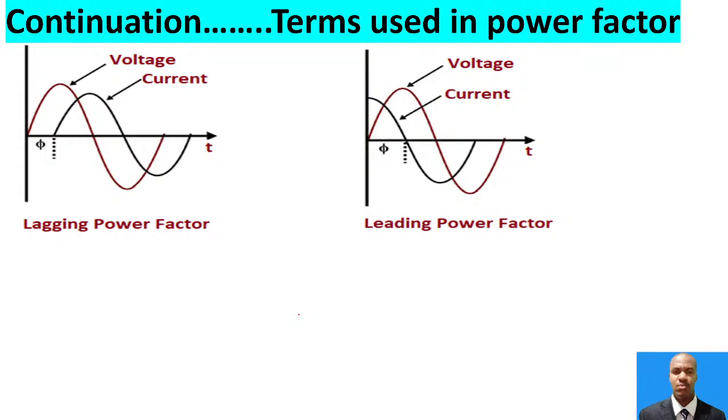And with me here is just a figurative example. If you can see, in these two waveforms, we have the voltage here, and the voltage is behind our current. So that means current is leading the voltage, and it is leading by an angle phi. The angle phi. Then in that case, we say that our PF is lagging power factor. Our circuit is experiencing a lagging power factor, and on the other side,